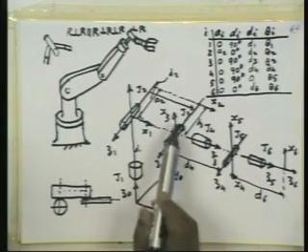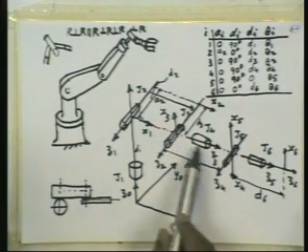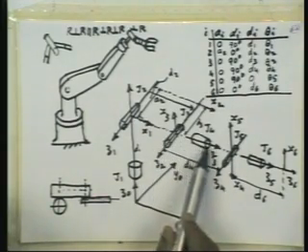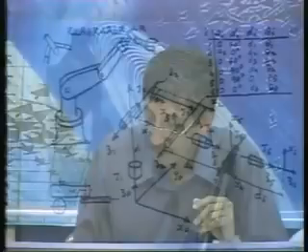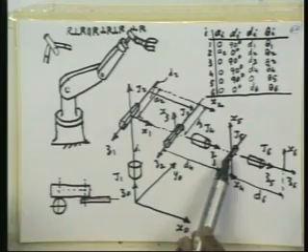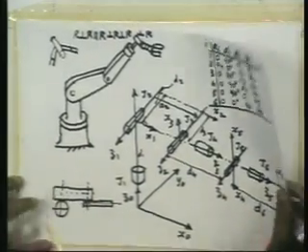So if you look at x3, y3, z3, this particular point, if you look along the z3 axis, comes at the distance d4 from the origin. So this point is nothing but 0 0 d4 in the third reference frame, fine. So this is the key concept used for solution.